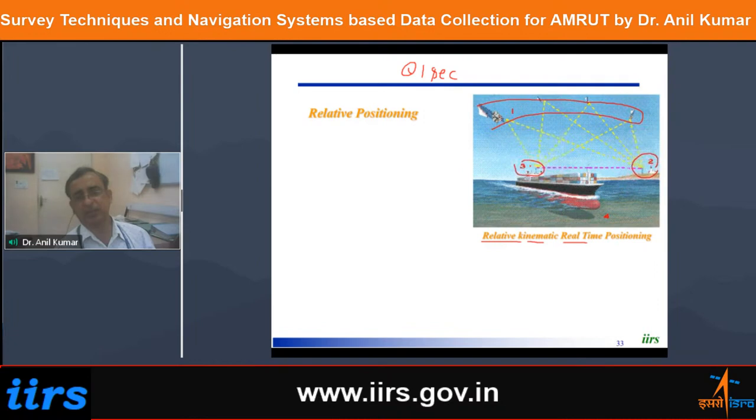And the distance between point number 3 and point number 2, practically, should be less than or equal to 20 kilometers. So we need to fulfill 3 conditions: both are locking common satellites, both are doing observation at the same observation rate, and the distance between both is up to 20 kilometers. Why 20 kilometers? So that the environmental conditions at point number 2 and point number 3 remain the same. Hopefully they remain the same. We assume that, and in that case, with these 3 conditions fulfilled, the error at point number 2 is common to the error at point number 3.